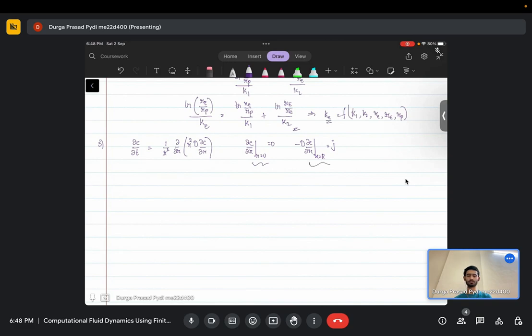You just have Neumann conditions on both sides, so you will not get a unique solution. You have to fix some reference value for a steady state problem. But here we have an unsteady problem, where the initial condition will give that reference value, so it can proceed.